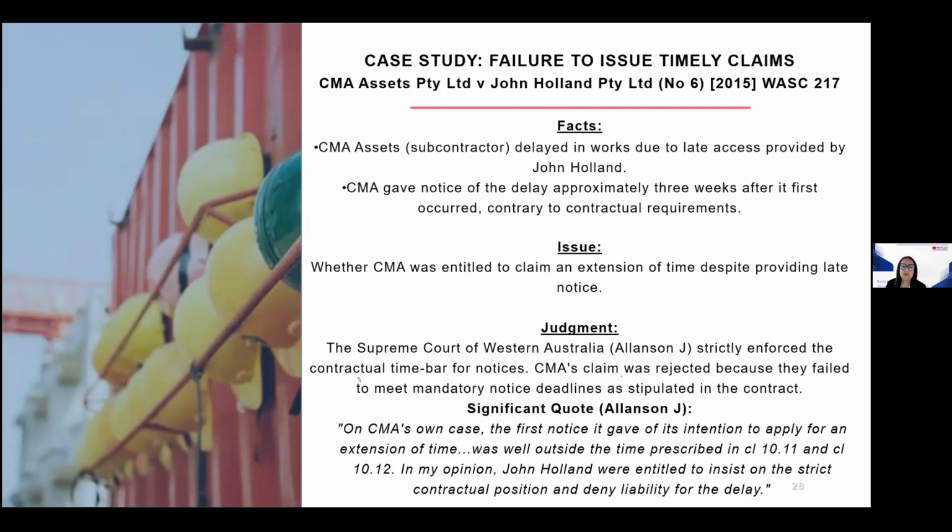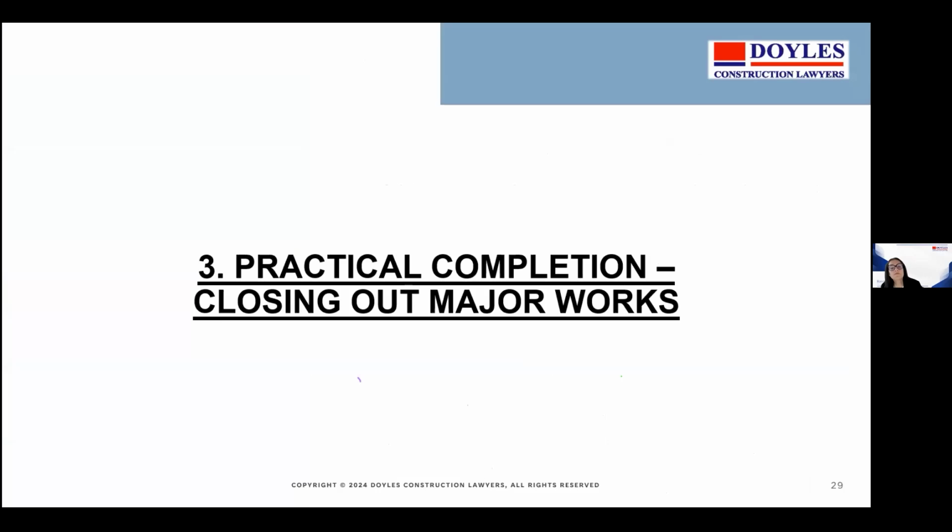Just moving on to practical completion and closing out the major works. So practical completion is a legal turning point. It affects liquidated damages, security, and defects liability, all these things that sort of come to a head at the end of the project.